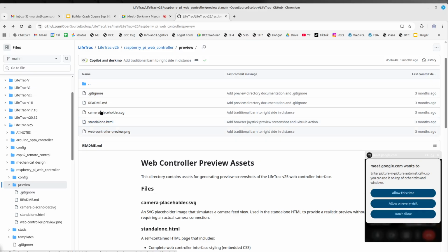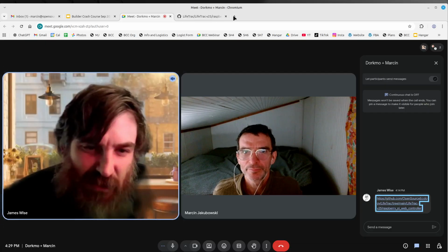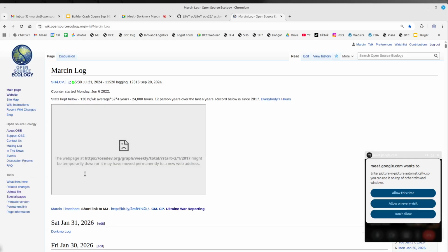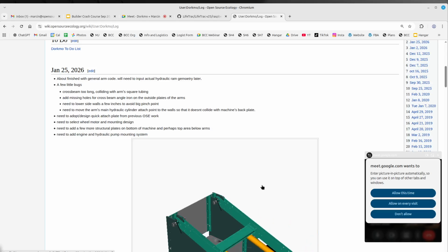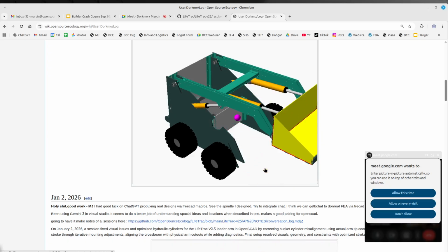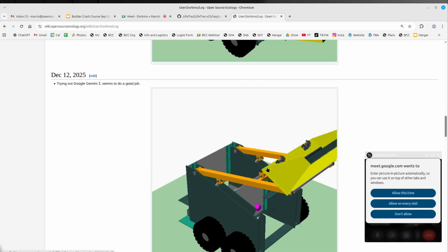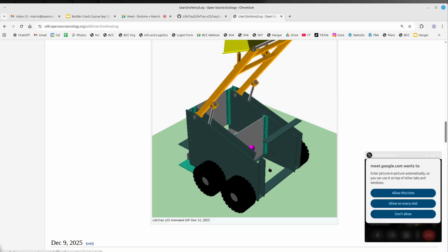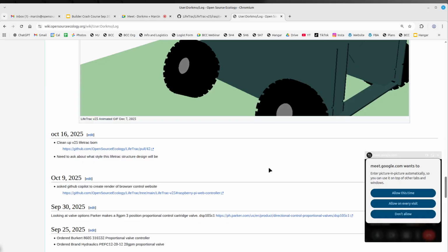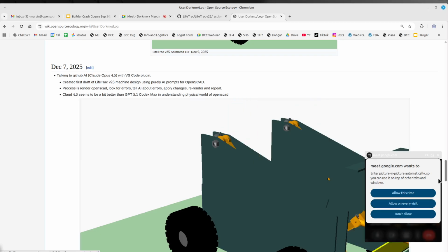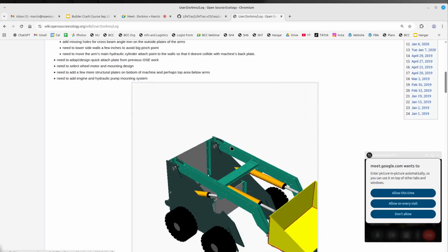It's funny, I saw there's a program you can download on Android called Droid Pad, and it has a Bluetooth Low Energy standard. Some of that Arduino hardware has Bluetooth Low Energy, so you can use that existing phone program. You have two joysticks, and then you can connect to the Arduino mounted on the tractor directly, so we wouldn't have to build any custom hardware. It'd be nice to have a hardware controller, but as a quick, easy thing, you can use a phone app.